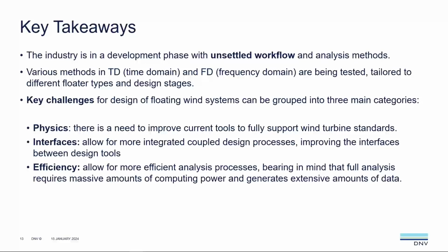And in relation to the frequency domain models, one of the things that we're looking at the moment is how to convert a detailed model of a turbine into something simpler, a mass spring damper system that can be coupled with these frequency domain models to at least partially account for the coupling between the two.